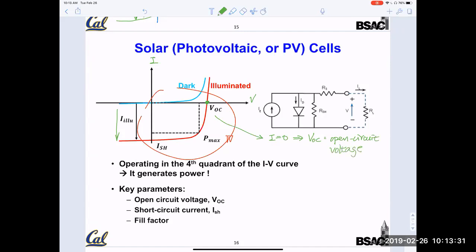So this means if you put a solar cell, it's literally an open circuit diode. When sunlight shines on the diode, a voltage develops at the two terminals of the diode. The polarity of the voltage is such that the P side will develop positive voltage. So this is kind of your VOC here. So the current flow is again opposite direction to that of normal current. So you operate in the fourth quadrant, and sunlight creates this area.